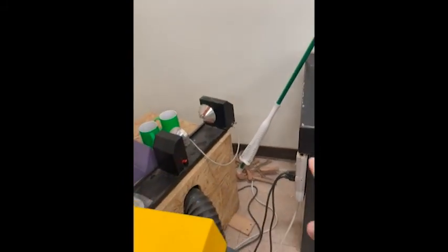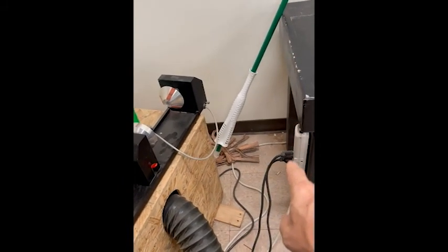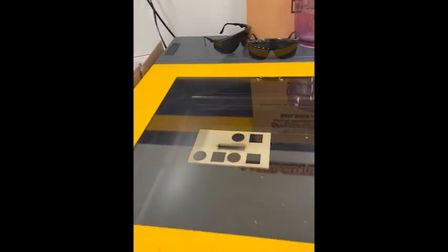The machine is turned on. And then over here, you have to make sure down here that the exhaust is turned on. This exhaust pulls out all the fumes and everything goes up and outside. So that has to be on. If you don't have that on, the laser cutter will not run. So now that I'm ready to go, I have the lid closed.